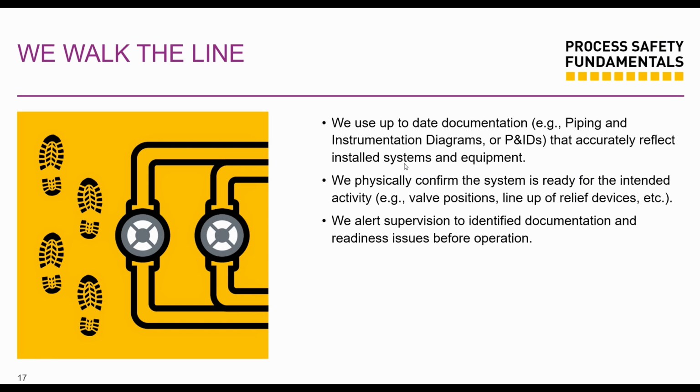You have another valve there. You have a temperature trip here. Stuff is being added over time. You want to make sure that you walk the line before starting any task, and physically confirm that the system is ready for the intended activity. Your valves are lined up, and your relief devices, your bursting disc, your PSVs, the upstream and downstream valves of your PSVs are open to make sure that they can operate.